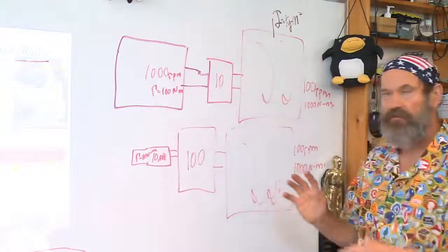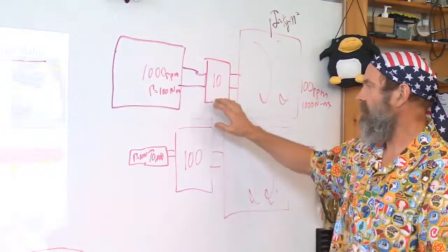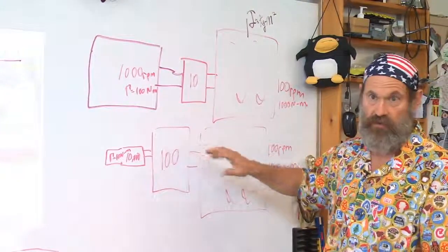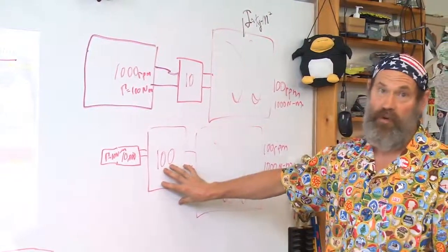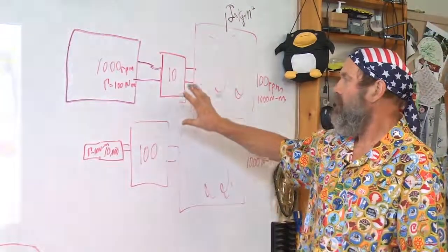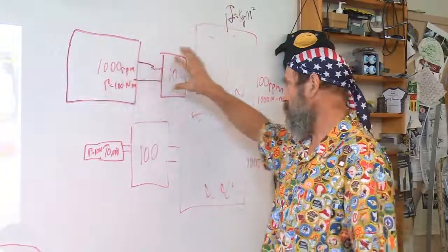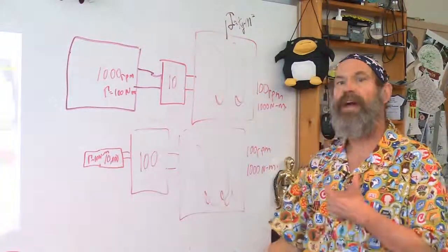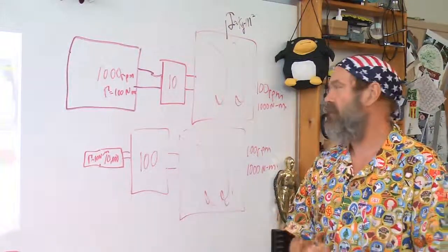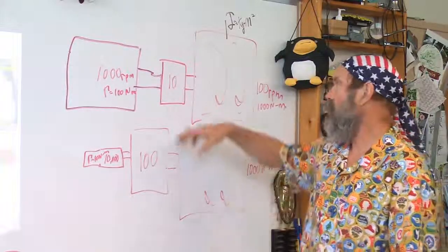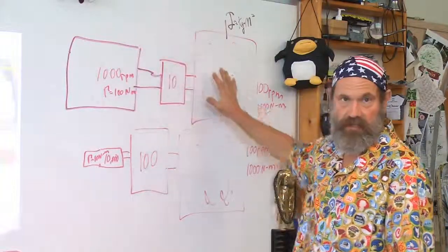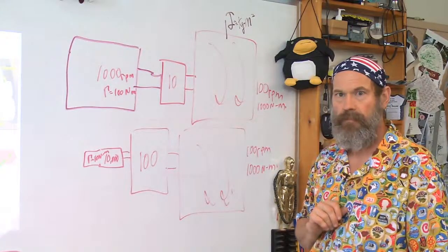And what will happen is you'll find that sometimes you'll get very unreasonable transmission ratios that are unobtainable, like 100 billion to 1. Very bad. So then once you get your workable scenarios, you go back and look at the physical cost of the items when you order them from the catalog, and you then minimize the cost. Okay?